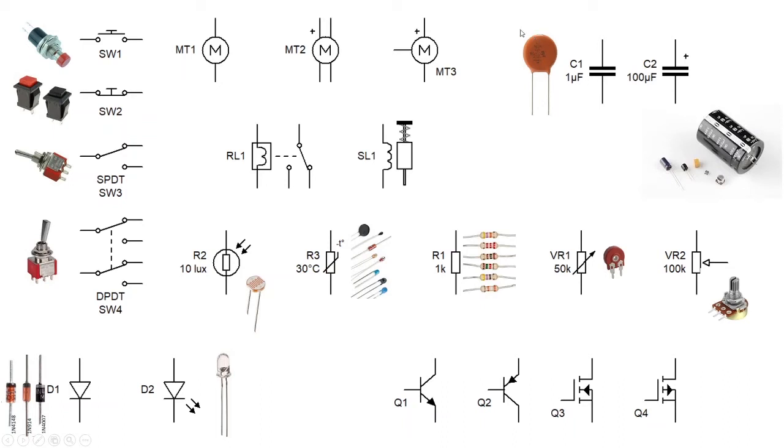Capacitors, I mentioned before, they look a little bit like these thermistors. These are ceramic capacitors, and they tend to be of a smaller measurement. And farads is the measurement of capacitance, which is basically, consider it like a very rudimentary form of battery. It stores charge. Now, it's not actually used like a battery, like a rechargeable battery. They'll be used to smooth out and sometimes delay things switching on as well. So we'll generally have them smoothing out spikes in noisy circuits. If you've got a motor or something like that, you might use a capacitor across the motor just to take out any spikes, because they will very quickly take up that charge but slowly fill up.